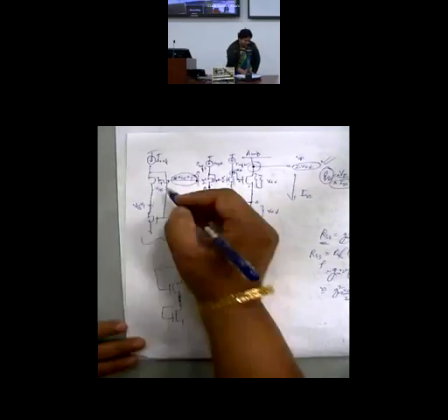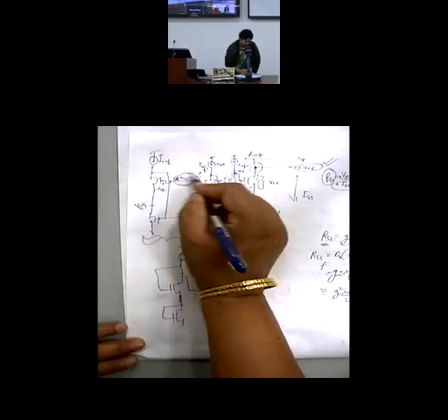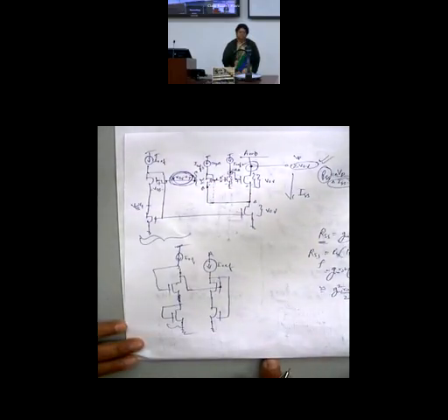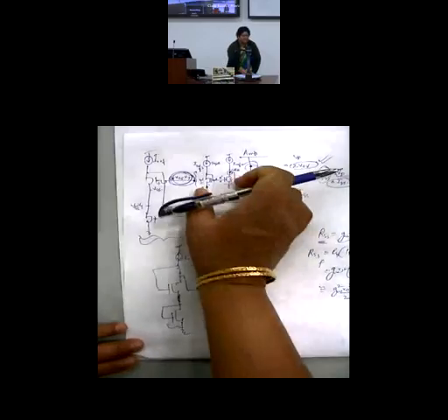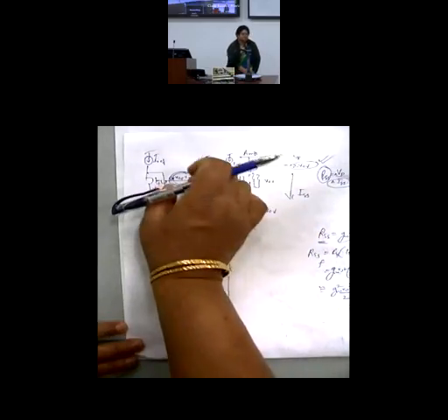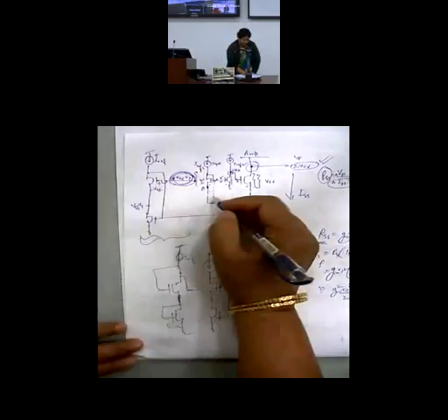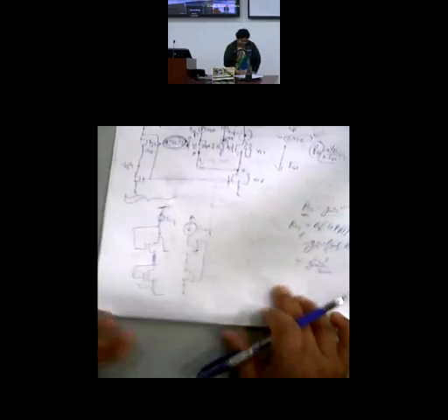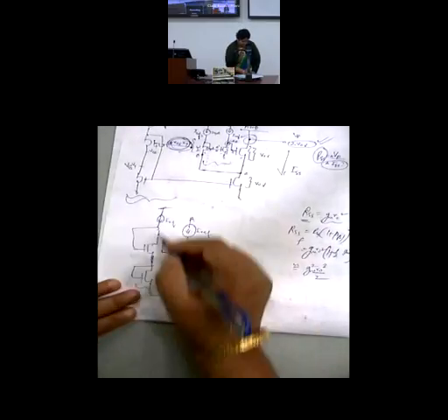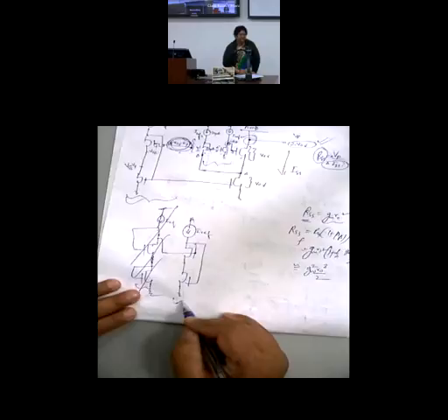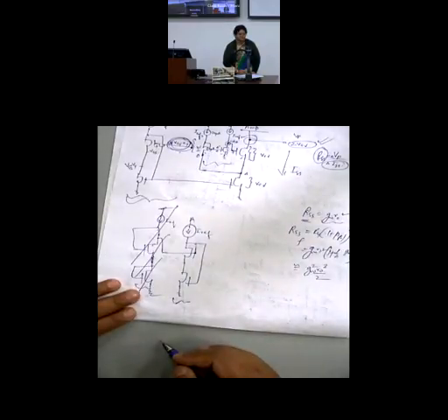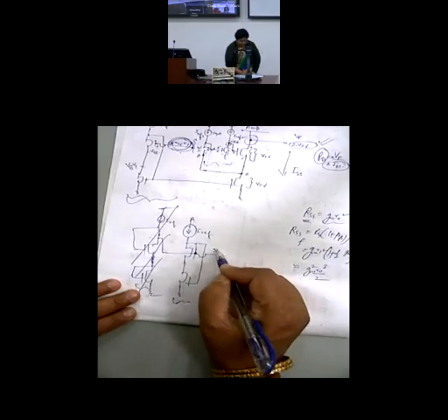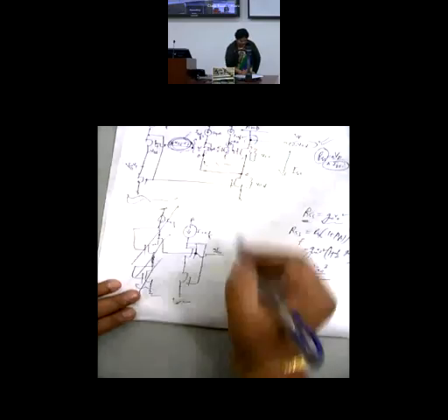Yes, for this circuitry I need to generate this potential, which I can do either by using this, or you can make a similar circuit for this also. How? I can make it like this. This you cut down. So I am making it for here. So this has to be VGS plus 1 V overdrive.